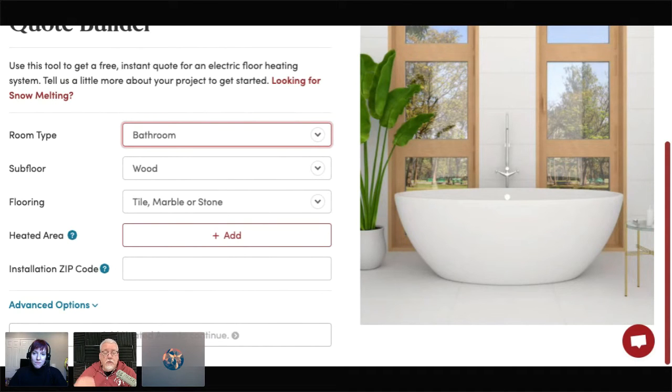We're going to default to 120 as long as it's under 120 square feet. And most master bathrooms are 50, 60, 70 square feet at the biggest. So keep that in mind. There's no need to go 240. You're saving a breaker space by doing that. So go ahead, Lynn. Yeah, absolutely. That was great information to have.